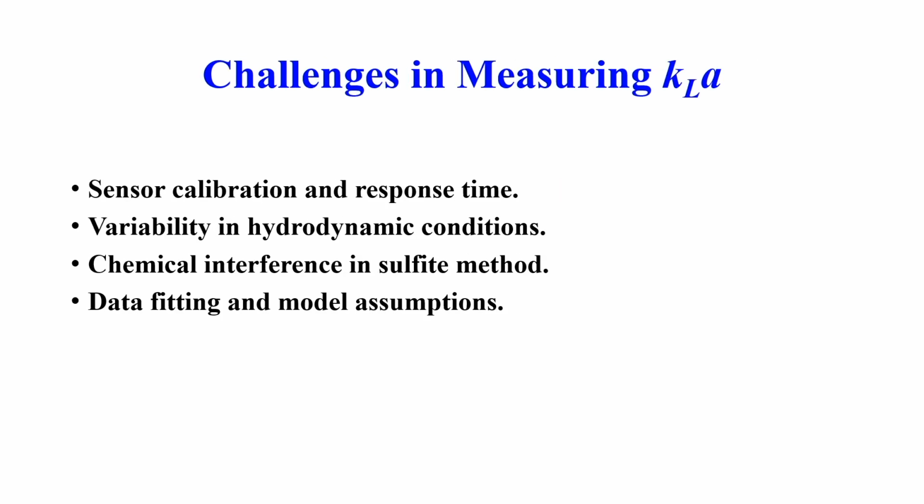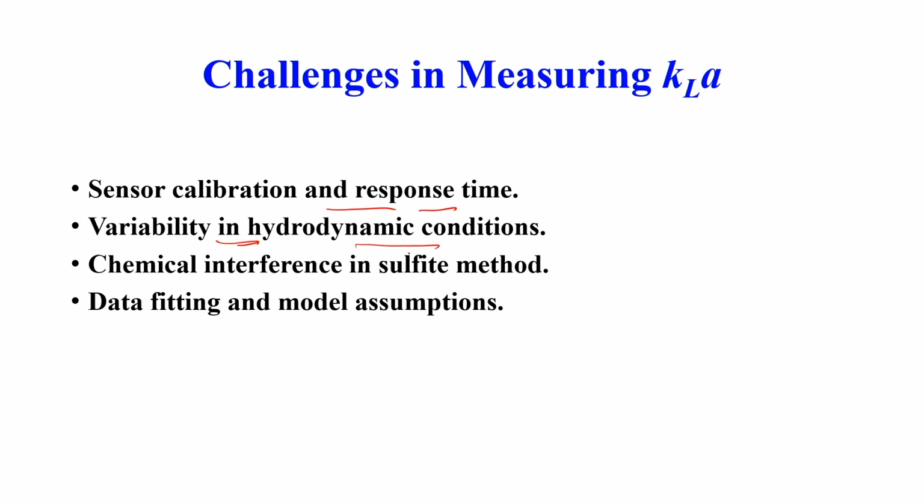There are certain challenges in measuring the KLa: the sensor calibration and the response time. The response time needs to be compared with 1 upon KLa, and there can be changes in the hydrodynamic conditions like flow rate and fluid property that may affect the oxygen transfer and then the measurement of KLa.